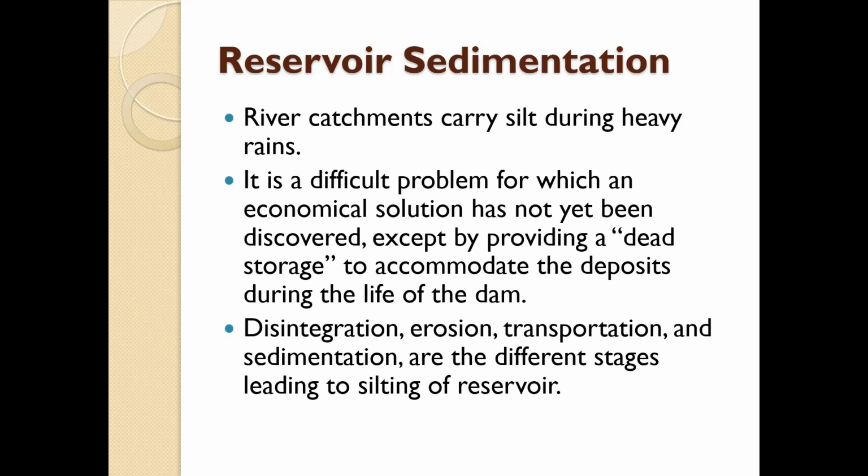The deposition of the sediment in the reservoir is known as reservoir silting or reservoir sedimentation. The deposition of the sediment will automatically reduce the water storing capacity of the reservoir. And if this process of deposition continues longer, a stage is likely to be reached when the whole reservoir may get silted up and becomes useless. Moreover, with the passage of time, reservoir capacity will go on reducing.